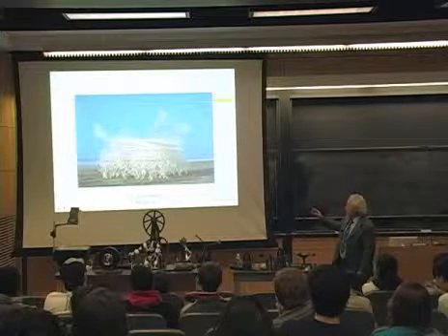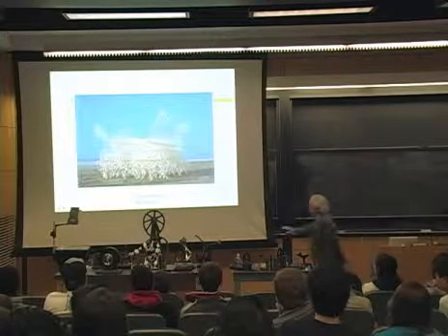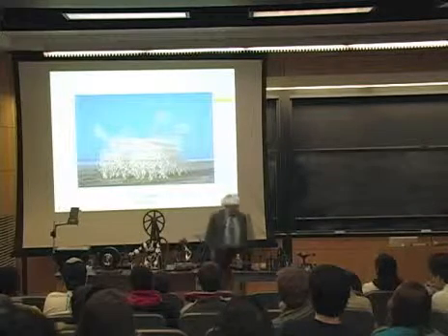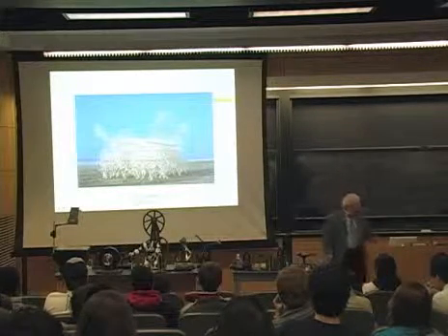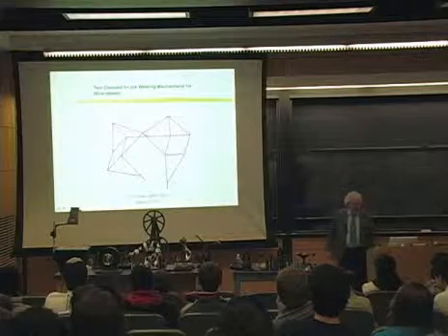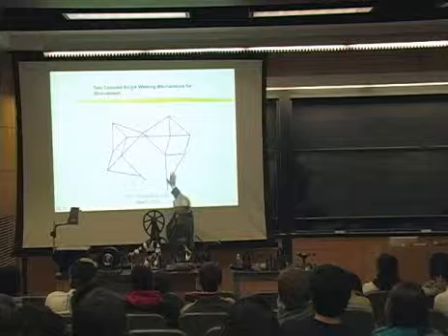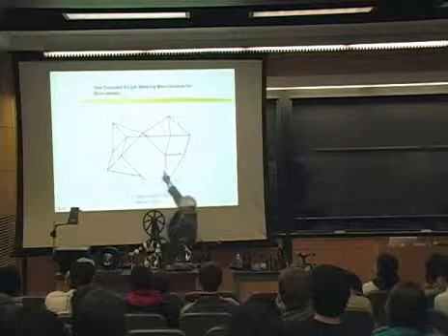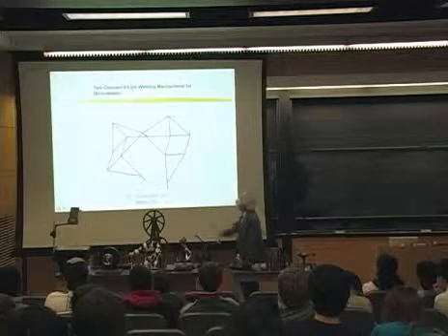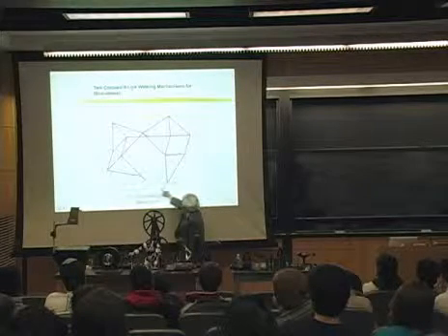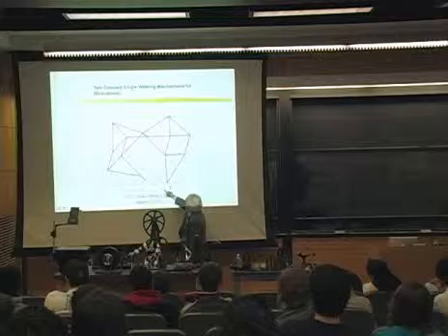But this system here can move in the wind, and each one of these leg systems can be thought of as a planar 8-link mechanism. So, in fact, this is the 8-link mechanism here. In fact, there's 2 of them, one here and one here. They're both sharing a couple of links there. And as you turn the crank, then this particular leg walks.